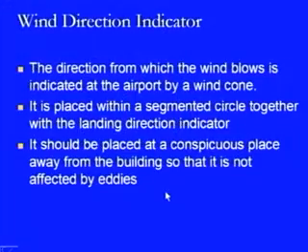Then it should be placed at a conspicuous place away from the buildings, so that it is not affected by eddies. If heavy wind is blowing and it is very near to the terminal buildings, then eddies will be formed, and in that case it will not be useful to the pilot to understand the behavior of the wind.